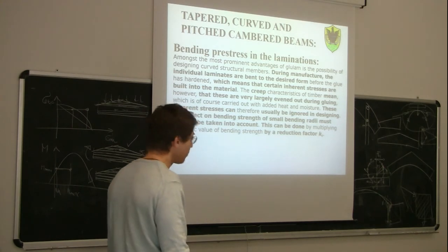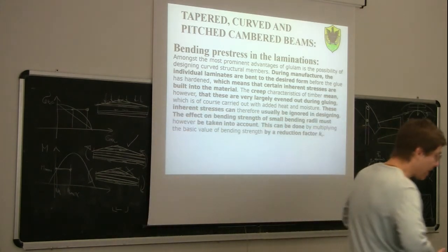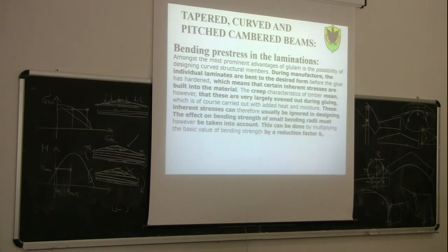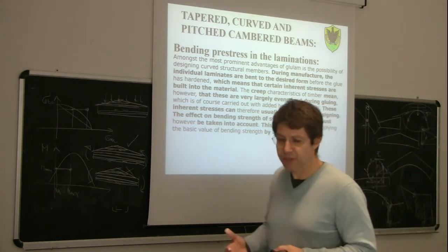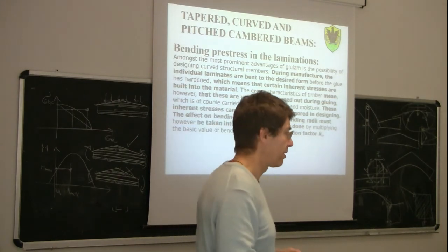Which means that as we bend the planks and glue them together, we induce some additional stress in the structure. Also, if you bend a plank, you need to apply a force, so you stress the planks themselves. Then you glue it, which means that you incorporate some eigenstresses, so autotensioni, in your structure. So your curved glulam structure, when it is formed, has some significant eigenstresses inside.